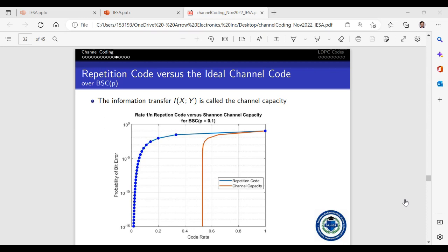Okay, so the low density parity check coding scheme has been introduced starting with 5G. Until 4G, the coding schemes were different. In 2G and 3G, the standards used what is known as convolutional coding. Then maybe around 3G to 4G versions of these standards, people started using what are known as turbo codes. And then 5G and beyond are relying on LDPC codes and polar codes. Okay.